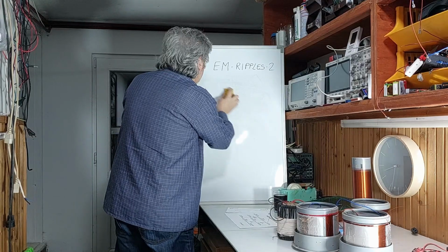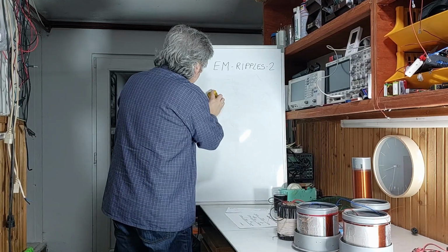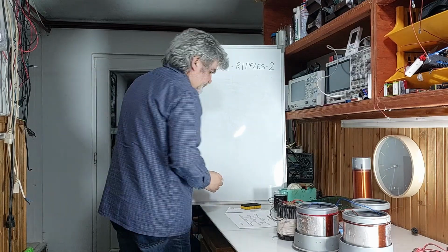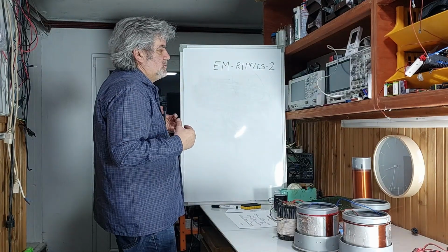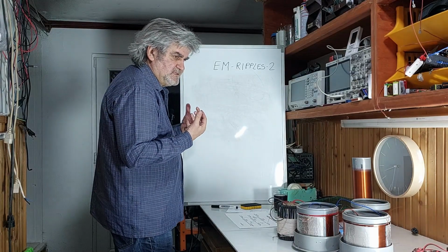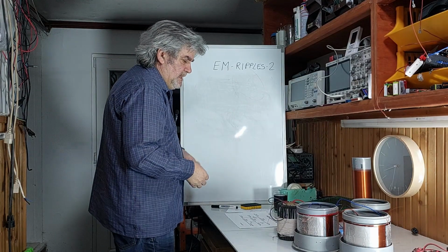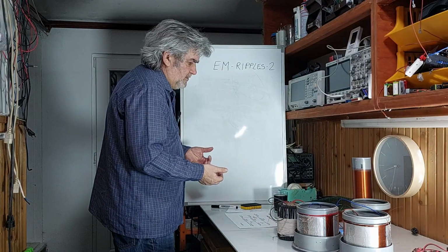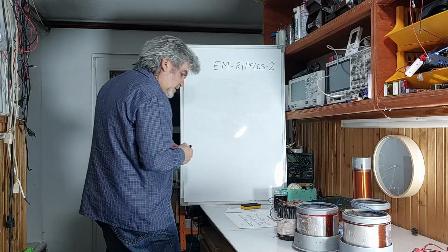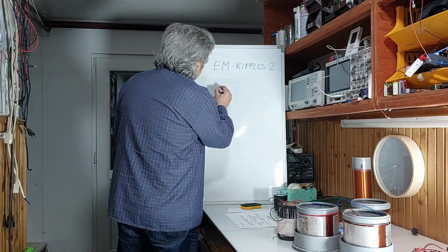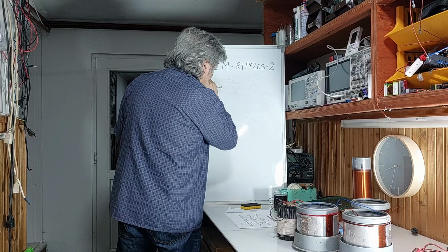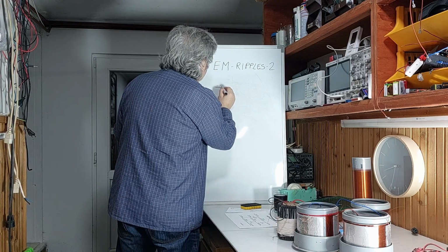Why this approach? The idea is to energize the coils while they are in series, and the back EMF is collected back into the battery when they are parallel, so as to increase the current. For 2 coils, I need 3 reed switches.